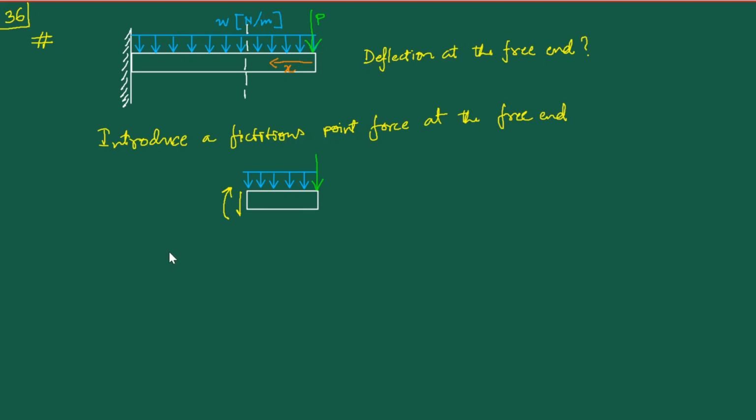Now what we are going to do is exactly the same as we had been doing in the previous lecture. We wish to find out this M, which appears in the formula where we use Castigliano's theorem of deflections. Let's write the equation for it. This M is in the clockwise sense, and the moment contributed by this force P about an axis passing through this end is P times x, and its sense is the same as this M, so it is plus Px.